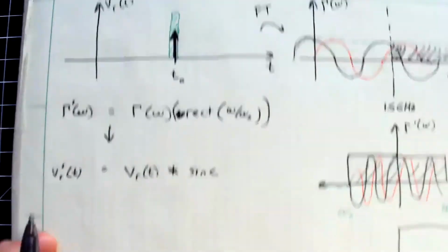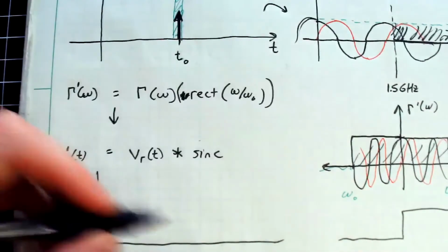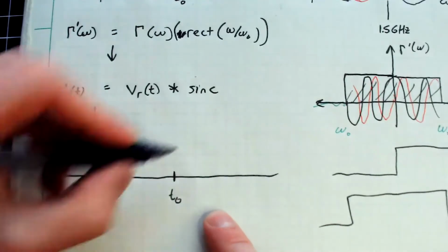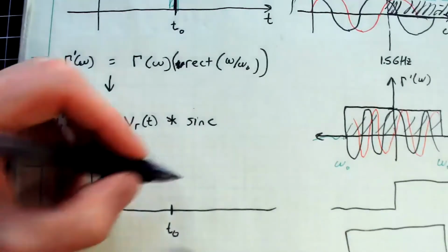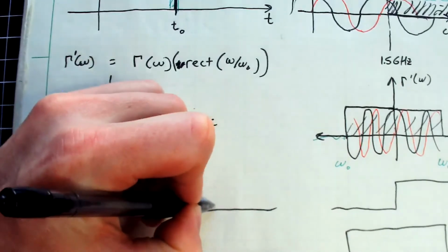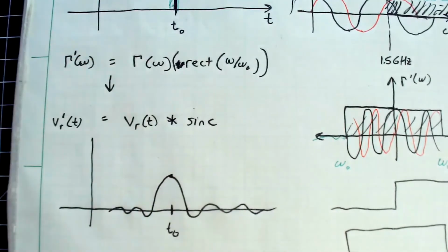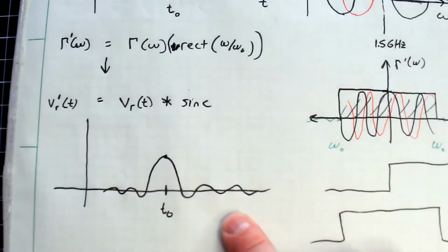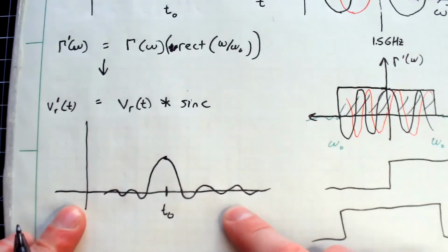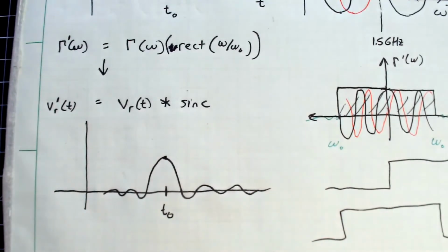So what you see in practice will actually look like the following. I had this little time offset here, and instead of having that delta there, what you actually see is a little peak, and it wants to do this instead. Like that. So this is actually what you are measuring when you take a band limited measurement of that with that nano VNA.